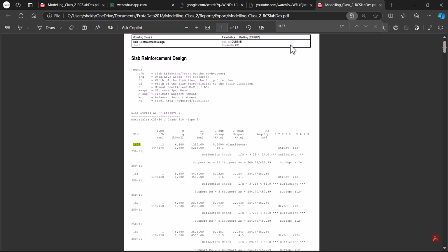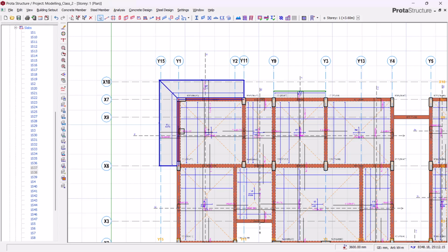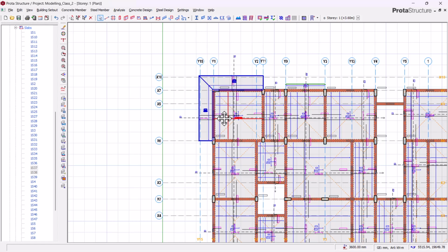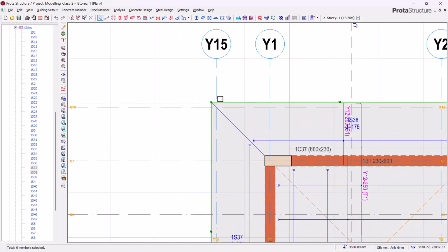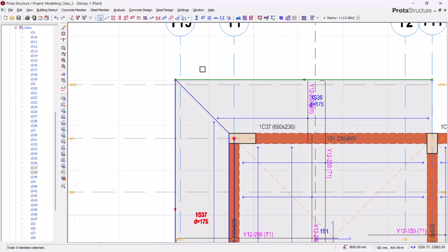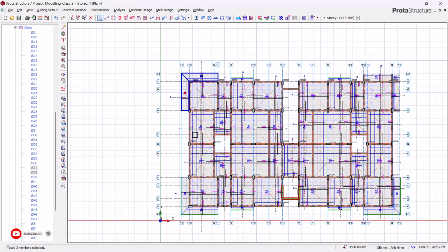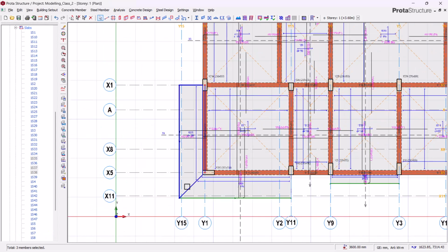So this is okay. That in turn tells us that we have to increase the thickness of all these cantilevered slabs, and not just on these stories, but on every other story. All right. So if you are sure you'll be monitoring the process of construction, you can choose to go with 175 thickness. But for the purpose of design and uncertainties, and also the quality of materials that will be used in construction, since I can't account for that, I will be going with a 200 thick slab for this cantilever.